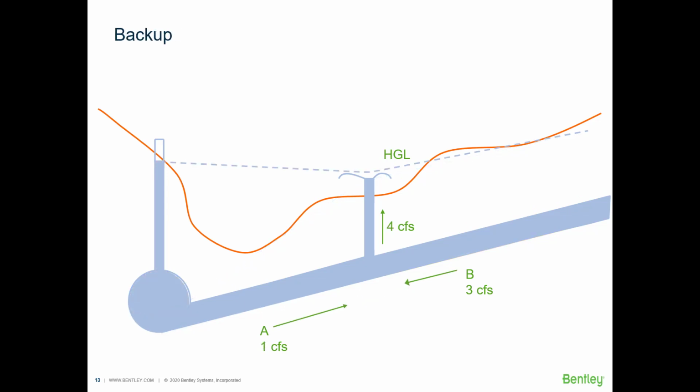So this is a good situation where you would want to use dynamic solvers. Now, if the surcharge is a result of a downstream backup, then hydrologic routing doesn't work, and it becomes necessary that you use the full dynamic wave equations. So really, the more complex the situation, the more likely it is that you will need to use a dynamic solver.